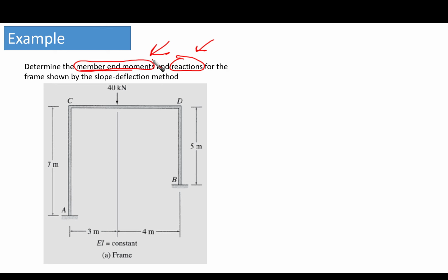Fortunately also BD and DB are not loaded, so the fixed end moments for BD and DB equal 0. This is very nice and makes our calculation simpler.